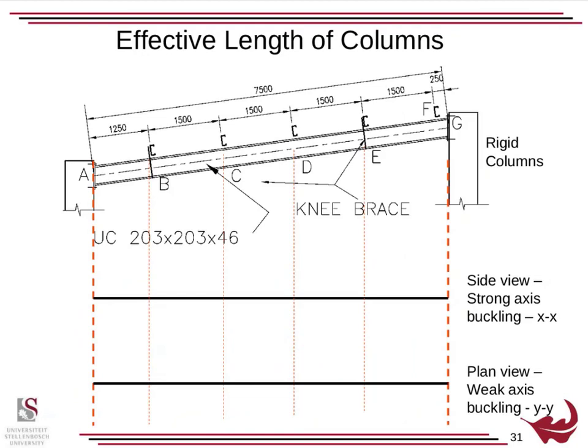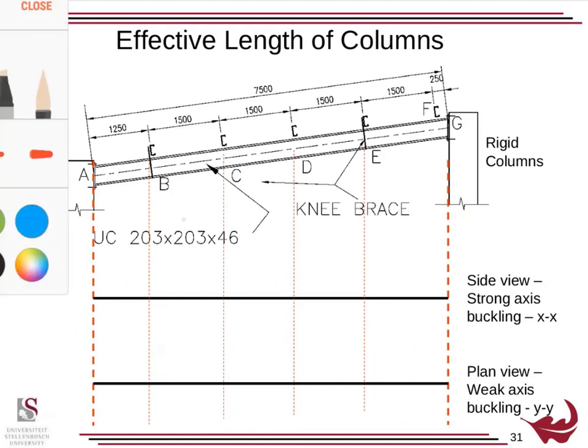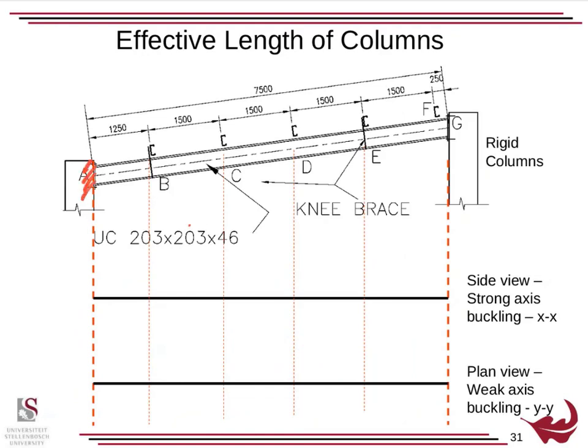So let's go on to this one, and I'm going to go through this one much quicker now after we've gone through everything. We've got a fixed column. There is now, let's say, this axial load. It's part of a frame, and now there's axial load acting on it as the entire structure tries to move. And we've got purlins on top. The purlins carry some sheeting, so there's some sheeting there. That is not drawn, but the sheeting is carried. And now we've got a knee brace.